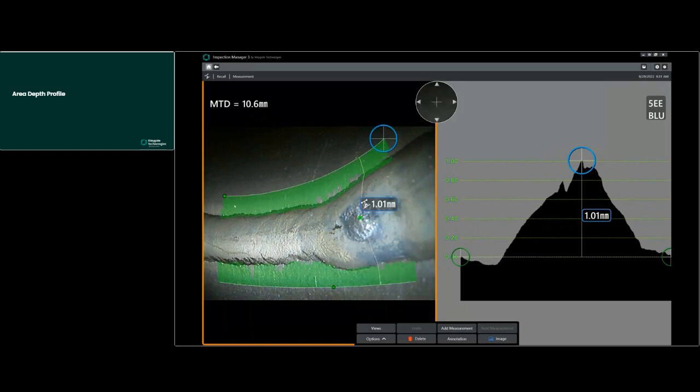Another thing to point out, the green masking here, we call this the 3D surface mask. As it's going through these individual slices, it's identifying points on the surface that are close to the reference plane for that slice, and it's masking those points in green for each slice. So basically, if a point is shown in green, that point is very close to the reference plane of one of these slices.